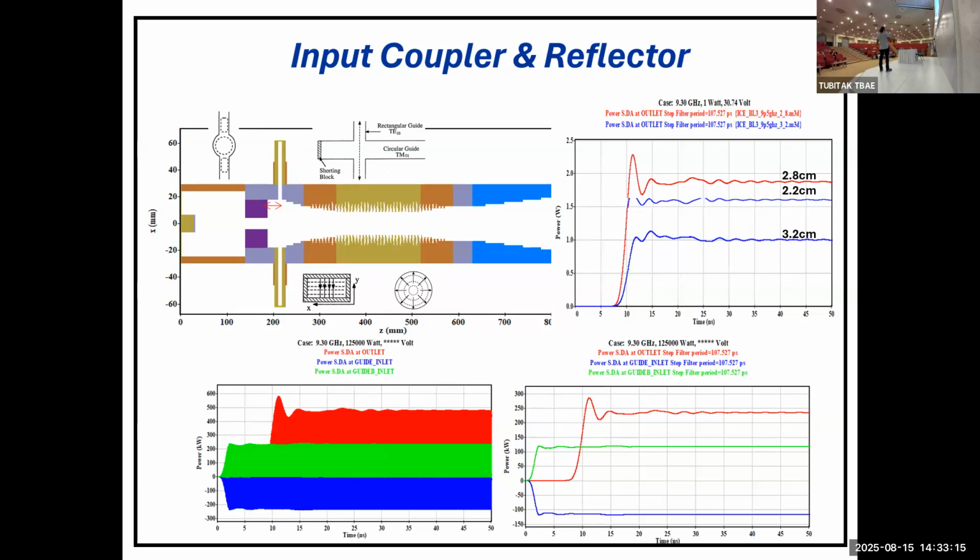It's very hard to have a splitter at high power. If you have a 100 kilowatt input signal and you want to split it, you end up with a very challenging structure. So you inject your RF power on one side, and on the second one you might use a plunger to tune it, to adjust and get the optimum coupling.